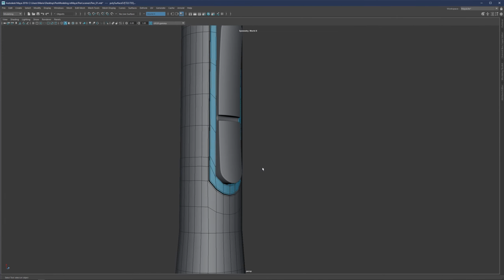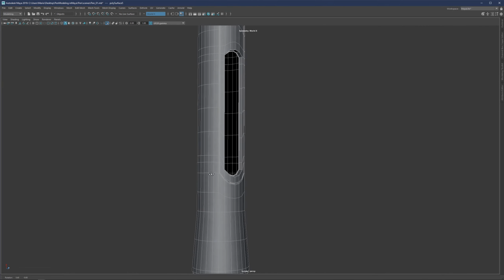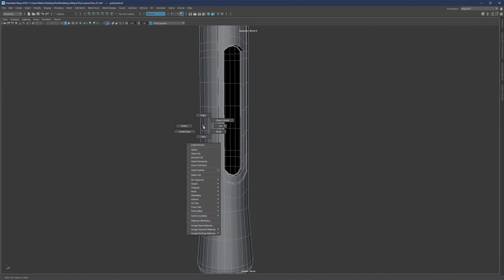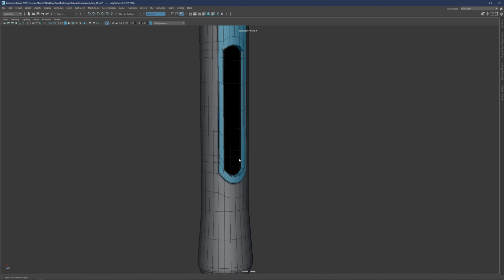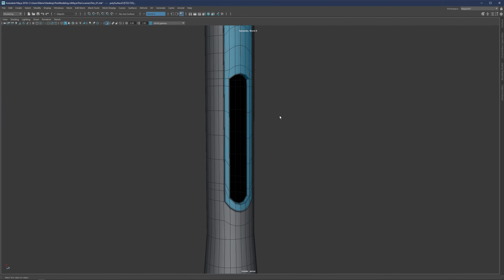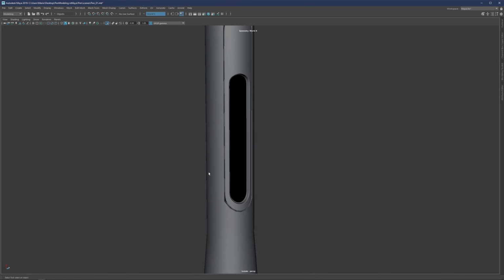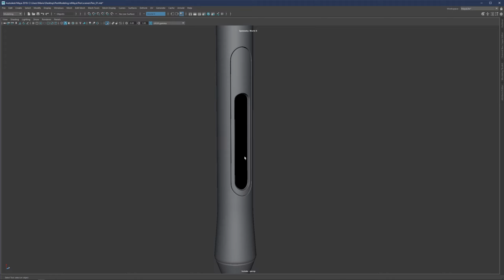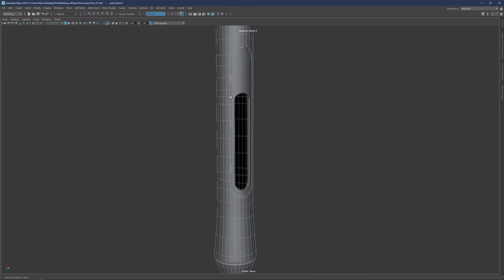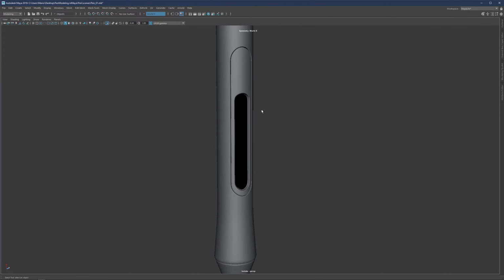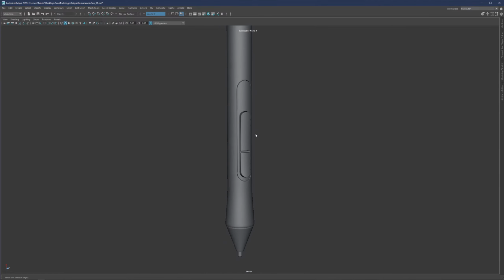And now this is again going to be a separate selection. With this separate selection, we can again press Control-1 to isolate it, go to face mode, and just double click on any polygon, and this will select until it goes furthest. Then we can go to Extract Faces and hit Q to confirm. Extract Faces does just like it says, it extracts our selection from the object. So now what we have are 3 separate objects.